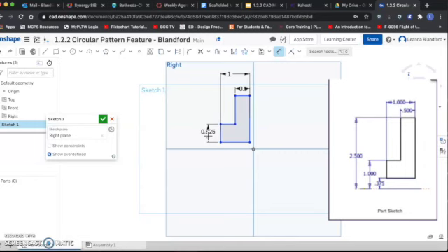So that gives me that bit. Then I need to subtract from the distance in order to dimension this line right here. I have 2.5, but I can subtract again to get that area. The dimension I am looking for is 2.5 minus the 0.625, which gives us that distance in there, and then we subtract the 0.375, which gives us 1.5. So we're going to change this to 1.5. And there I go. Now that's similar to the shape that I'm seeing inside of my drawing.